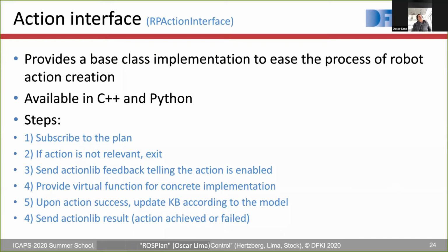So let's say for execution, if you want to execute the actions that are inside your model, what you need to do is inherit from this base class, which is the RPActionInterface class. And then once you inherit from there, you implement a virtual method, with the concrete implementation of what you want your robot to do.